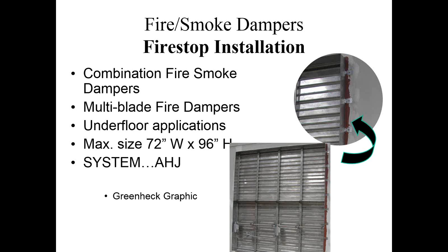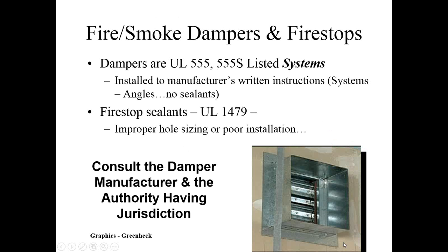That fire damper test is quite amazing, where they burn it for a period of time, and then at the other side of the damper where the ductwork is extending, there's a drop test where they drop a 55-gallon drum full of sand, hit the duct to see if it'll knock the assembly through the opening or out of the opening.